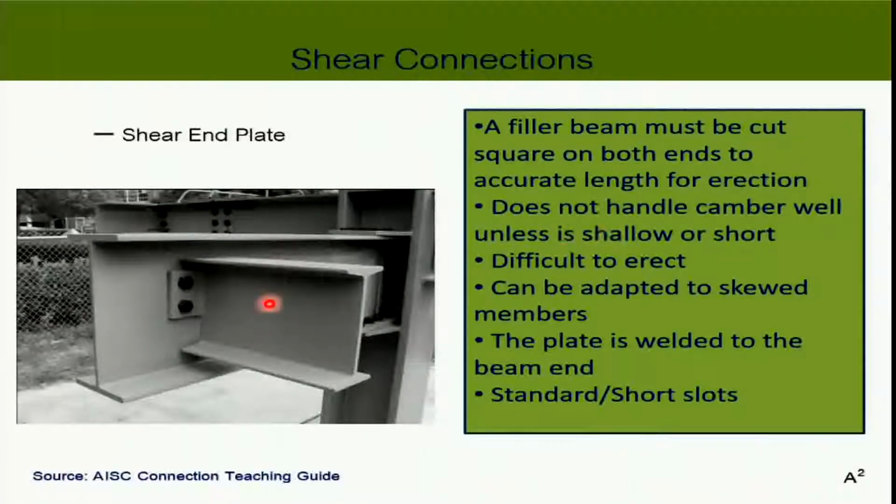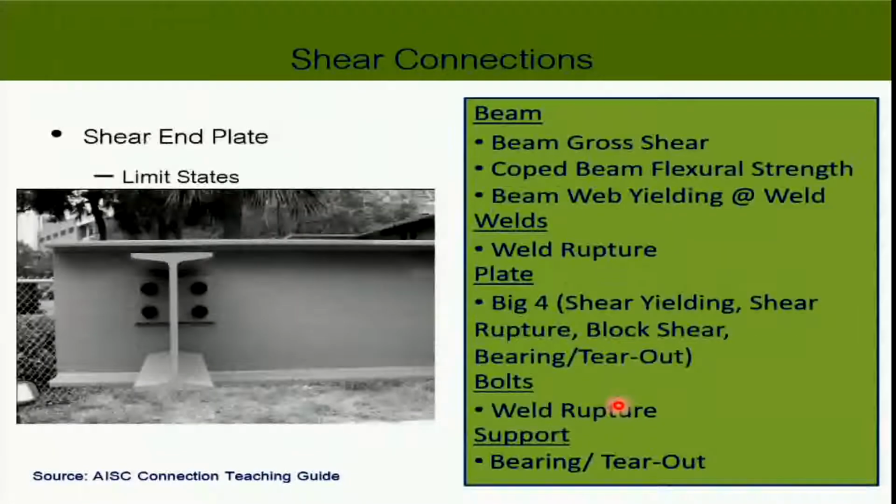And if you need to do the camber to counter the deflection problem of the beam, this one is no good. Can't use it, because the camber will come down to zero level after the deflection from the dead load, right? So that means you have no means to install this. So if you do pre-camber, this type of detail cannot be used with that. Okay? See, difficult to erect. And okay, now let's go into details.